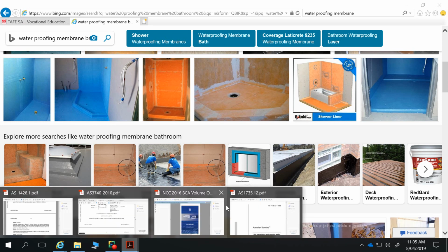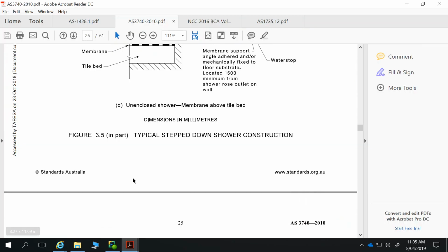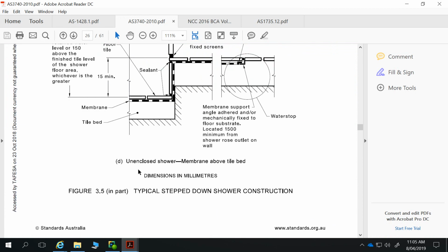So that waterproofing membrane has to go onto water-resistant substrates. So it's not only about things in your bathroom having to be waterproof in certain sections, but also water-resistant in other sections. And this is also an important part of your waterproofing details.